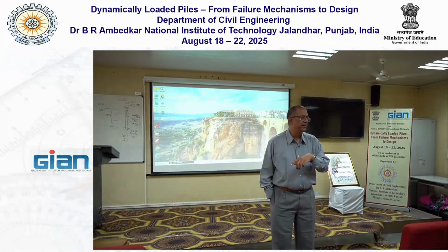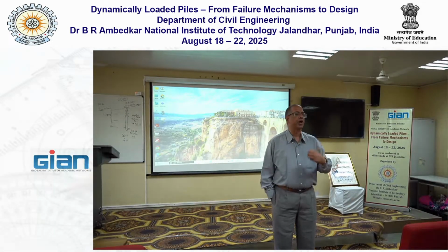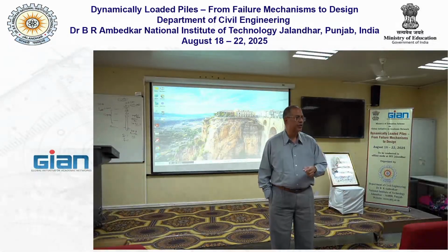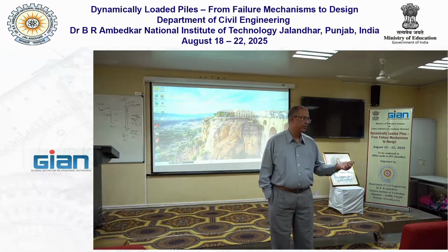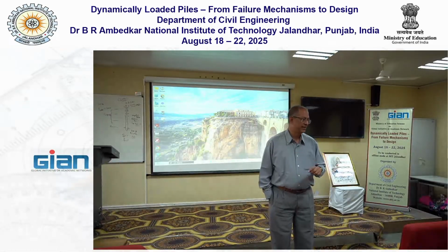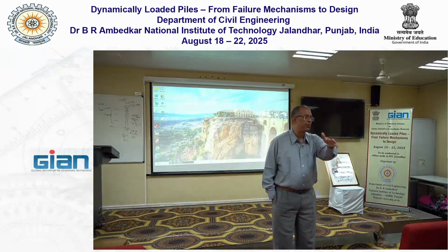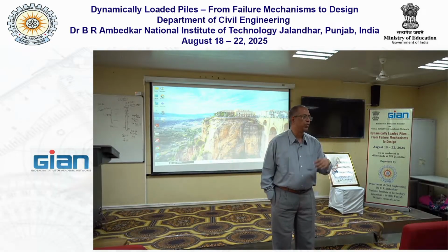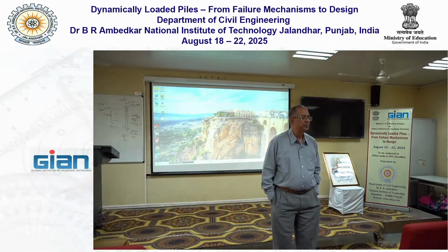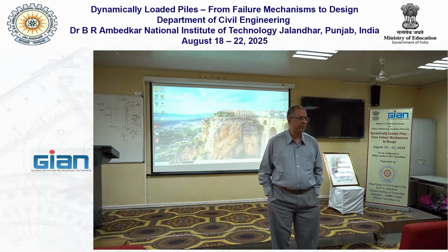With soil around it, the factor of safety should come down, because the downdrag is adding as an extra load on the shaft, and you lost the shaft capacity, therefore your factor of safety should come down quite significantly. And some of you showed me numbers of close to 1, which means the pile has a risk of failure. Okay? So that's what should have happened.